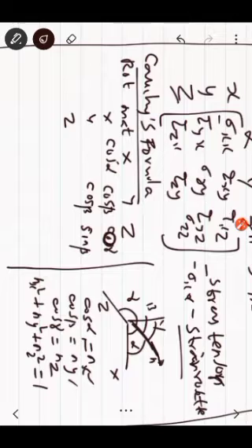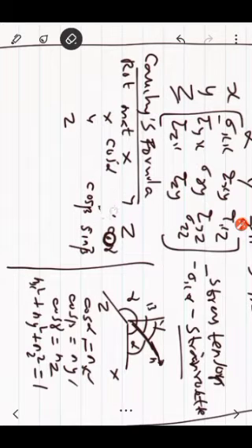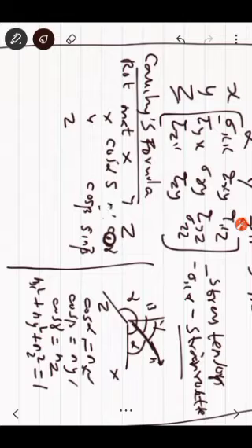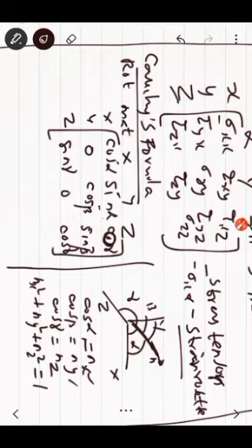The angle between x and z, you will be having 90 degrees. So this can be written as sine beta, and this can be written as cos 90 minus beta, you can write it as sine alpha, and this is 0. In the same way here you will be having cos gamma, this is sine gamma, and this is 0. So this is the rotation matrix. So you have to multiply these two: multiply the stress matrix and the rotation matrix.